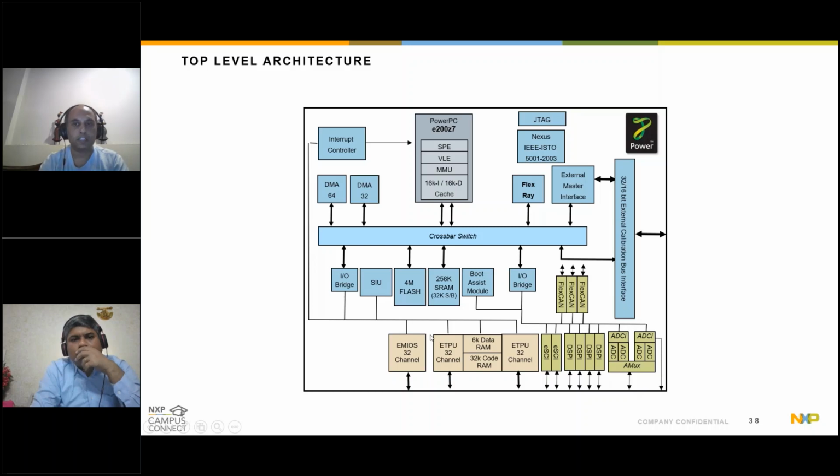This is just a simplistic block diagram, but there will be many other things in a typical SOC block diagram, let's say for system level clocking or arbitration or some of the other functionalities. But this was just to give you a flavor of how market to product requirement, to architecture definition, to detailed design technical specification, and at the end of the day what you might get, is now translated into RTL from here onwards.